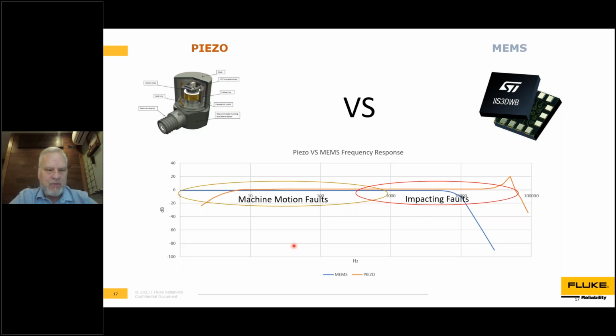Low resolution sensors, many that are on the market today, can give you many of the machine motion faults. But particularly when it comes to bearing, gear, and other very highly critical faults in a machine, you only get notification of those very late stage in that fault. So we tend to call them hand raisers, these low resolution sensors. They're not early indicators, they're just late stage indicators when there's actual condition issues going on with a machine, whereas we are all accustomed to being able to measure and be somewhat more predictive, and so we need that high frequency range in order to get that predictability.